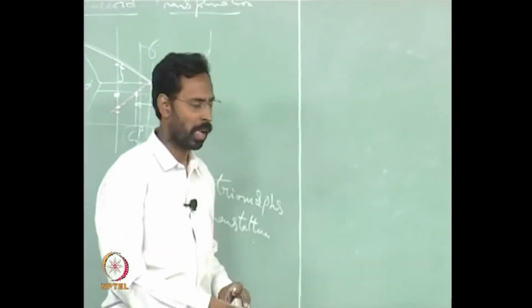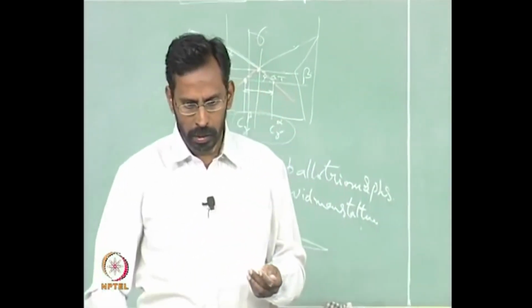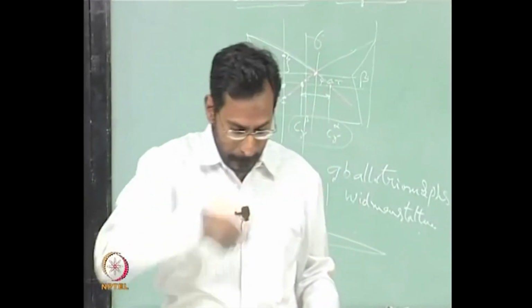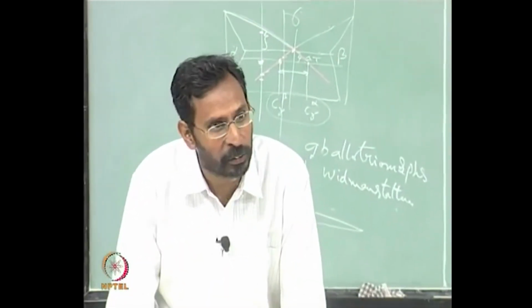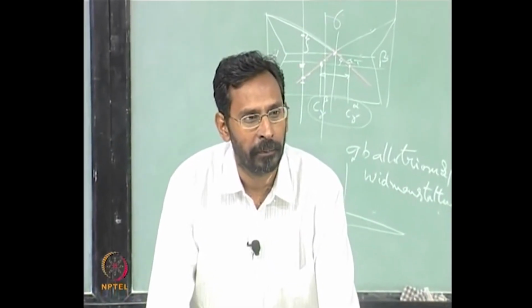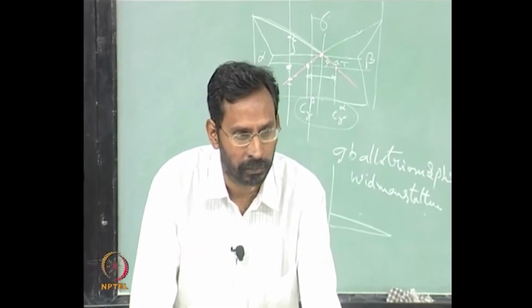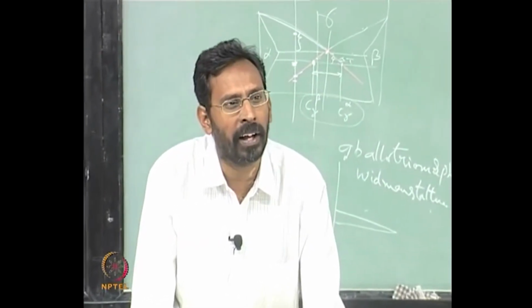In iron carbon alloys, we are getting chunky carbides because of the interfacial energy of cementite and carbon. Yes, that is not in eutectoid. Please, eutectic. Yes, tell me. The same interfacial energy logic has to be applied for eutectoid also. Why are we getting a plate? Yes. The reason is because it is a solid state.